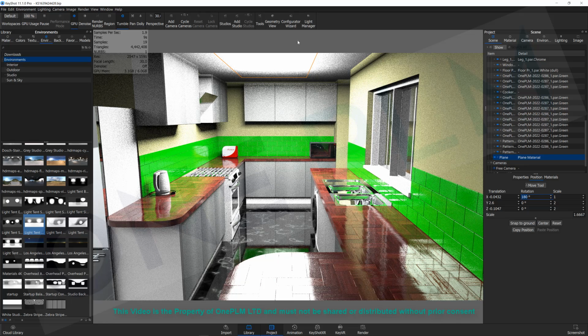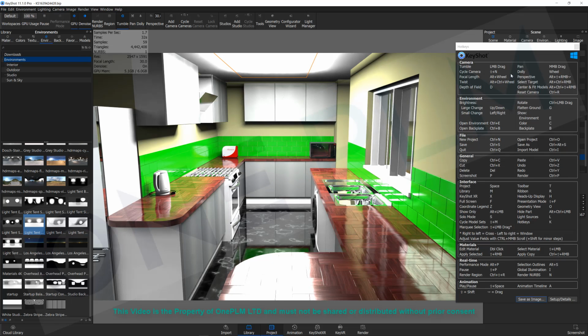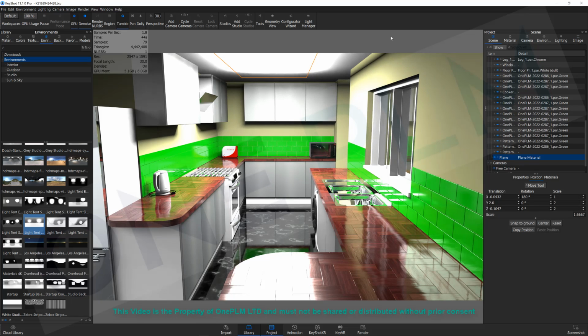Okay, so we can now either leave that rendering on there, or we can use this little denoise option to reduce a lot of the fuzz. So quickly we're going to get something, and that's just going to keep running. So we've got all this information on here. This little box can be turned on and off. If we press K on the keyboard and bring up our shortcuts, that will tell us how to turn this on and off. I can't remember straight off the top of my head. Heads up display, H. So that will turn that on and off. Yeah, H.